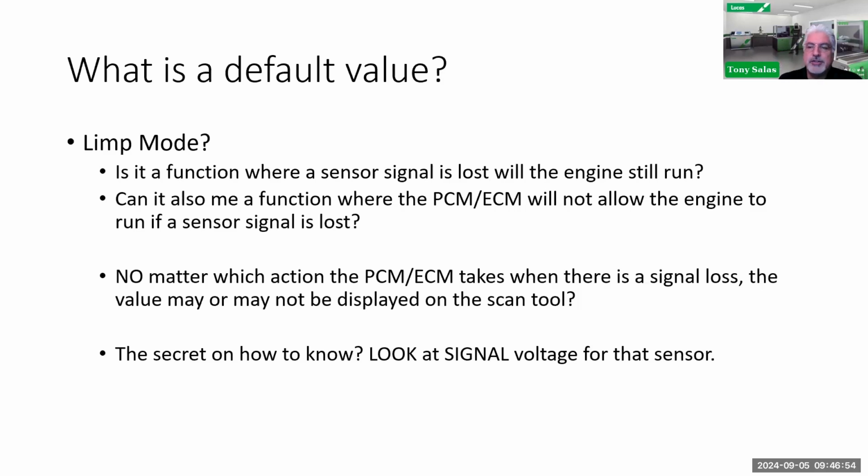But what we like to do is we'll go up to the battery, we'll get the starter cable, we'll hit the positive post, crank it with the key on, the engine will start, then it kicks it out of that lock condition. That's a classic example of a limp mode, right? So what happens when you disconnect the fuel rail pressure regulator on a Duramax? You'll get no acceleration. The default action is, when it sees it can't control the rail pressure, it won't give you any acceleration, right?